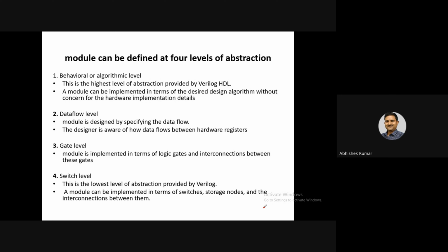The third one is gate level modeling. In this case, modules are implemented in terms of logic gates. Here we have to write the program and specify which logic gate we are going to use. So here all the hardware is defined by the design.